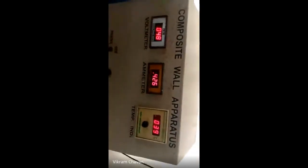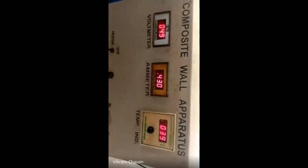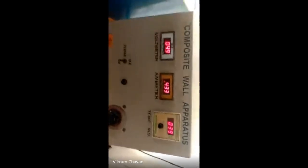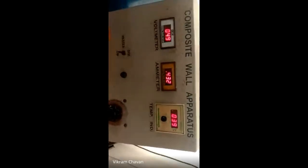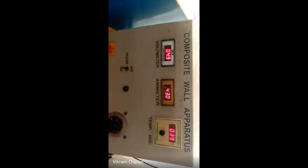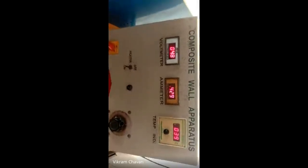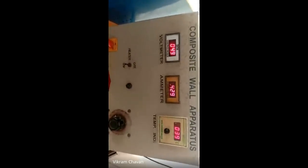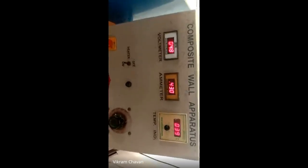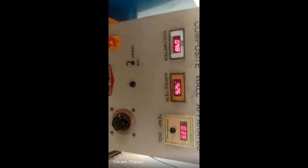So please check whether it is matching with the previous reading or is there any change in the two readings. So it is matching. When the current reading is matching with the previous reading, then the final reading will be considered for the calculation purpose, as the steady state reading, because on that basis we can conclude that the temperature will not vary further with respect to time.